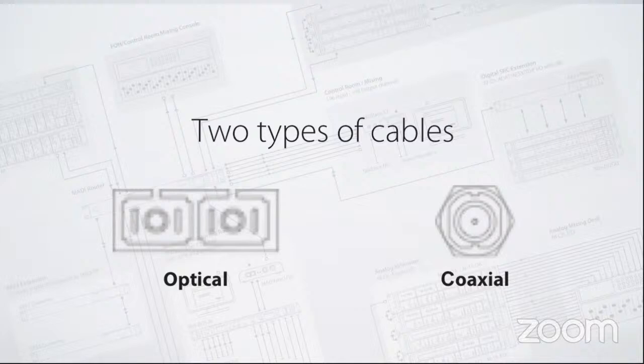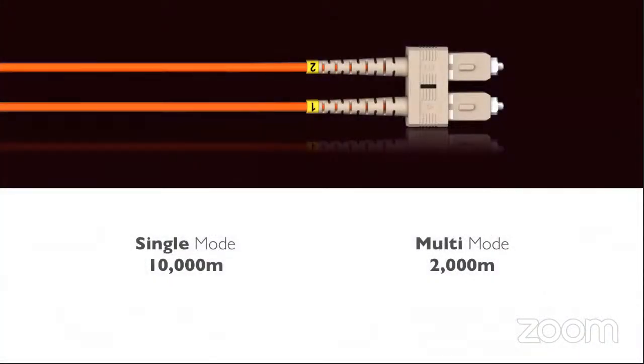Now, there's two types of MADI cables, and arguably there's really three, because you will find twisted pair Cat5 MADI, but the most common are these two, optical and coax. Now, the optical looks like this shot that you see here. This is a duplex MADI cable where you have this little connector attaching the two cables so you can insert them easily into the in and out respectively. But you can also buy MADI cable as a simplex version, which is just the one cable by itself.